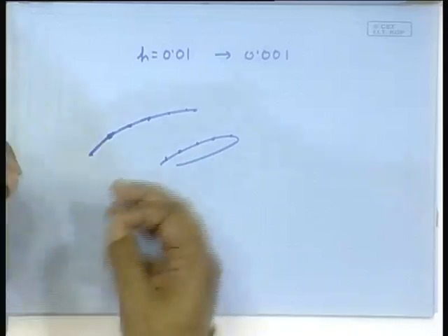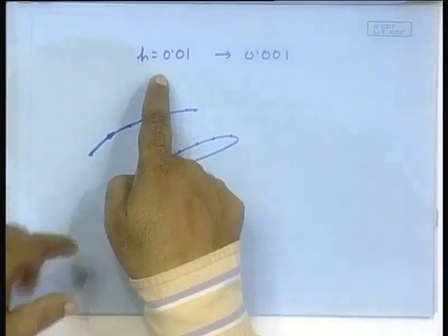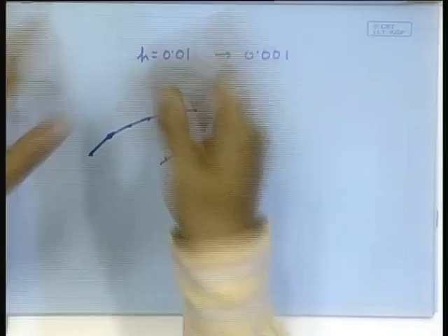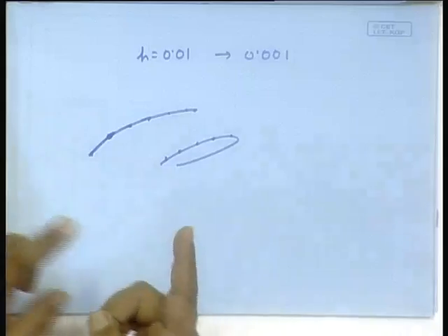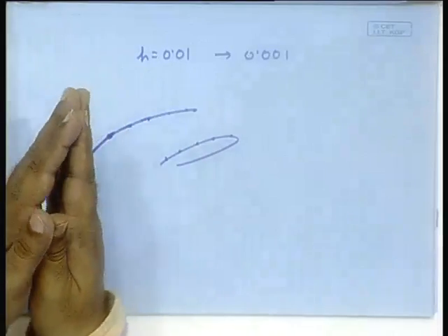Something is oscillating, say, at megahertz frequency and something else is oscillating, say, at hertz frequency, then you have trouble, because something is really oscillating very fast and therefore your program should be tuned to that frequency. That means the h step will be so small as to be able to see those oscillations also. But if you set the h larger, then you will be completely missing those oscillations.